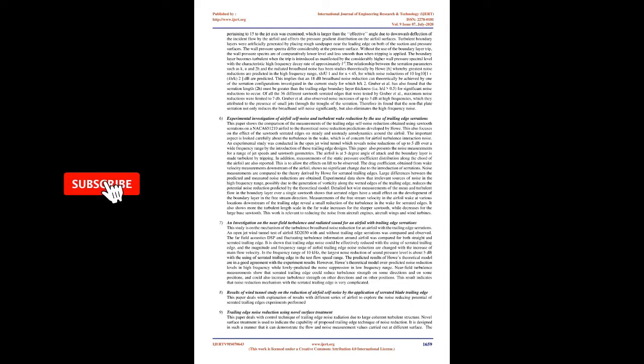The observed values are compared with Howe's theory, which shows noise reduction levels predicted by Howe are much greater than the measured ones. The main parameters investigated in this paper include the unsteady wall pressure, power spectral densities, PSD, coherence functions, and heat transfer characteristics across a full sawtooth surface. It shows that noise reductions take place up to 7 dB over a wide frequency range, whereas the noise is increased by 3 dB at higher frequency. As per Howe's theory, the angle between the sawtooth serration must be less than 45 degrees to reduce the noise at the trailing edge.